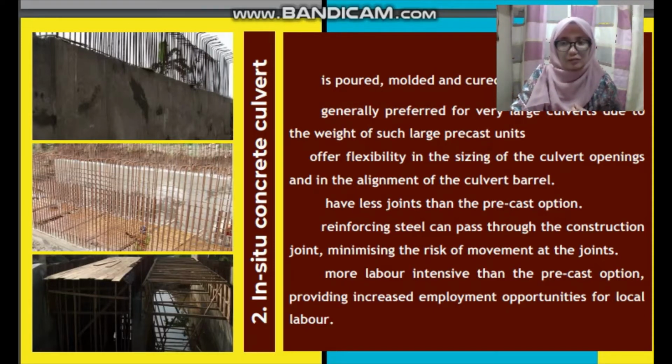Besides, precast concrete culvert requires more joints and therefore is less suited for earthquake-prone regions. For those structures in places where the structure needs to be earthquake-proof, in situ concrete culvert is usually the perfect option. However, there are very specific instances where in situ is the best approach.